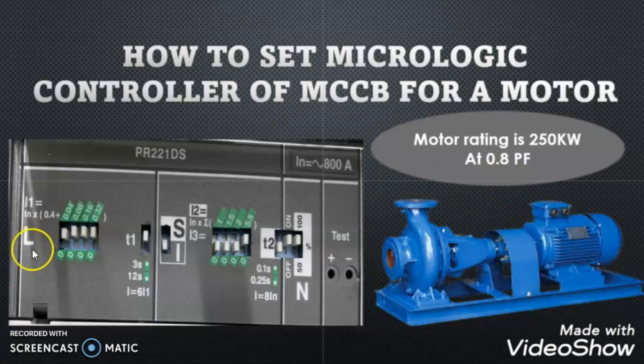Here you can see that there is a setting for L, a setting for S, and a setting for I. Here the L setting is for long time setting and the S setting is for short time setting. The L setting will give protection against the overcurrent, and the S setting, which is a short time setting, will give protection against the short circuit current.